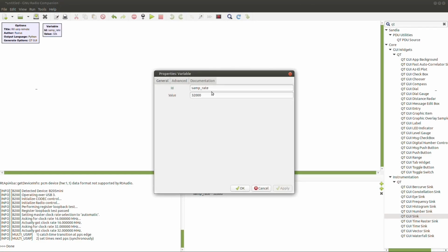We use a sample rate which will be convenient for us to get all the samples without problems. So yeah, by default, a lot of people use 1 MHz, which is generally enough for this kind of remote. If you want to also identify which frequency is used by the remote, we can always increase this value. For example, you can increase it to 40 MHz, and like that you can have a better bandwidth to identify in which frequency the signal is shown. But let's use 1 MHz.